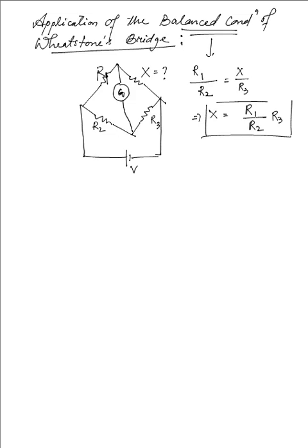Now a meter bridge is simply a bridging circuit just like the above, but the length is 1 meter, that is 100 centimeters. We have a scale to measure the entire length. This is more or less the circuit diagram for the meter bridge.